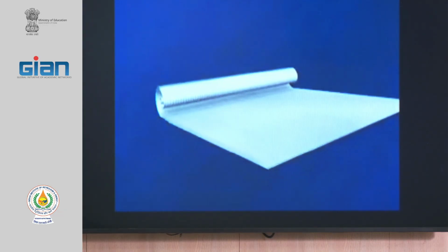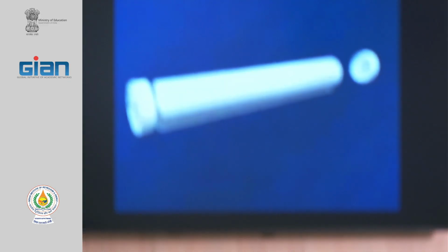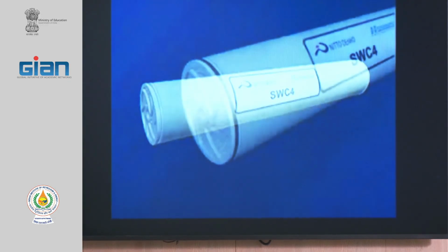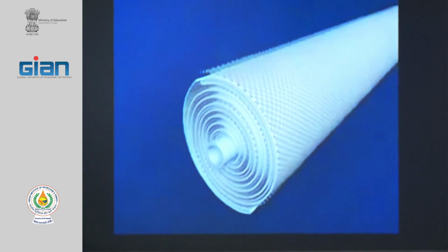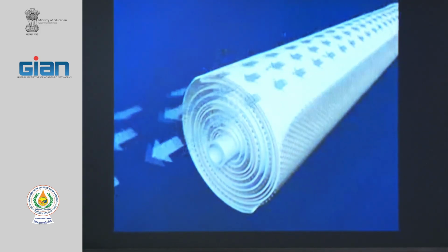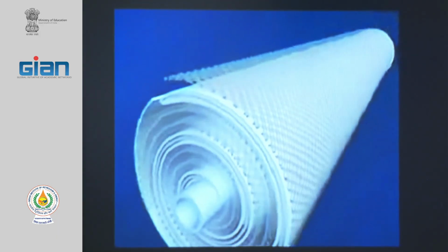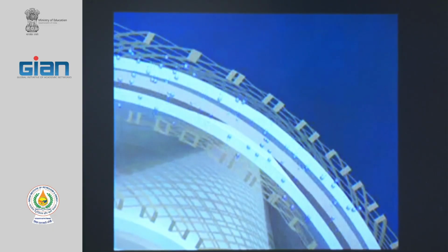And then rolled around the core tube. This is anti-telescope, and for pressure resistance, we have a fiberglass layer, about 3 or 4 millimeters of fiberglass coating, for pressure stability.